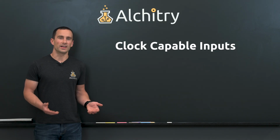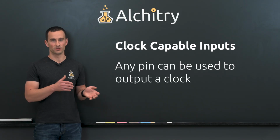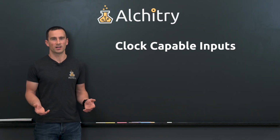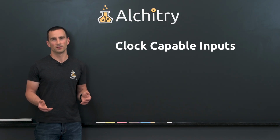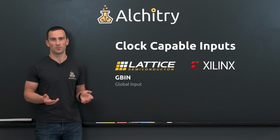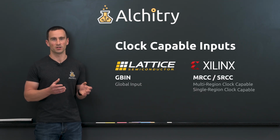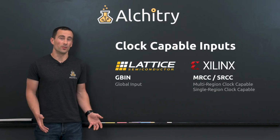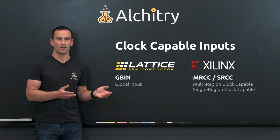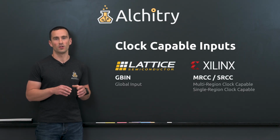It's also worth noting that any pin can be used to output a clock. There's a little bit of trickery involved due to the way that signals are routed internally, but it works for any pin. Different manufacturers call their clock-capable inputs slightly different things. For example, Lattice calls them GBIN for global inputs, while Xilinx calls them MRCC or SRCC for multi-region clock capable or single region clock capable, respectively. For the most part, you can treat MRCC and SRCC pins as the same thing. Either can be routed to the global clocking resources, and they differ only in their local clocking resources.